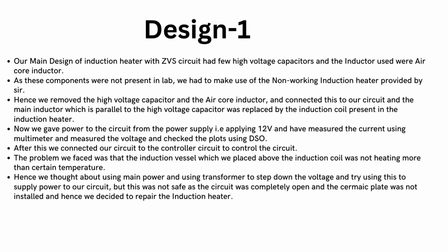So our main design of the induction heater with ZVS circuit had a few high voltage capacitors, and the inductors used were air core inductors. As these components were not present in the lab, we had to make use of the non-working induction heater provided by Sir. Hence, we removed the high voltage capacitors and air core inductors and connected to our circuit. And the main inductor, which is parallel to the high voltage capacitor, was basically replaced by the induction coil present in the induction heater.